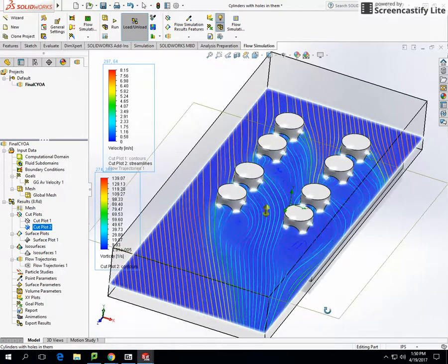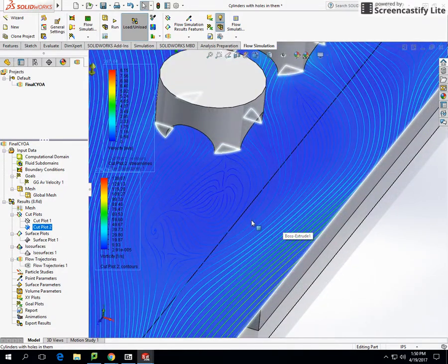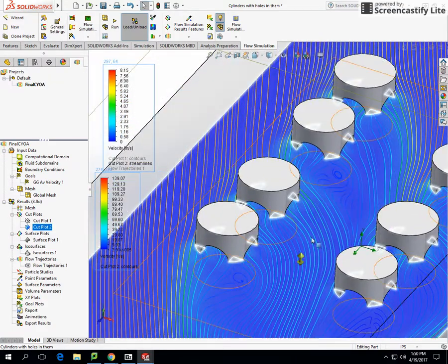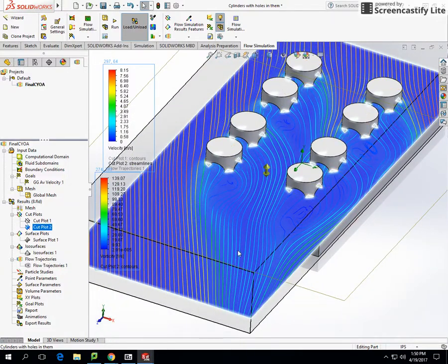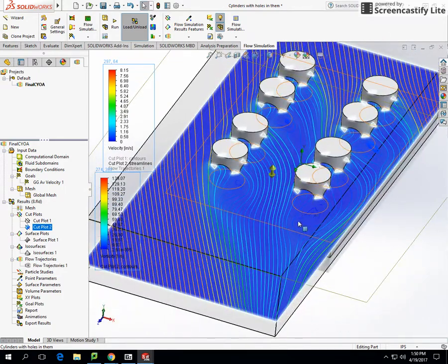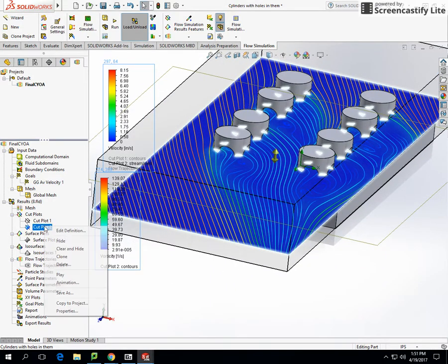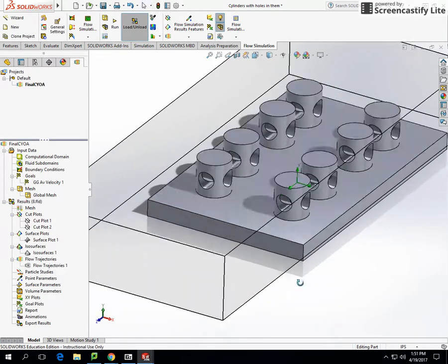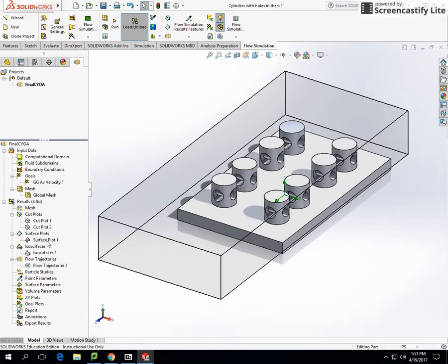This one is measuring both velocity and vorticity. So I have the contour showing vorticity and the streamline showing velocity. So these streamlines are showing the magnitude of the velocity. Darker is slower, red is faster, and then the underlying background color is going to show you the actual vorticity. So it's more vorticitous in the darker regions than in the slightly lighter regions out here, which is going to show you the eddies and all those sorts of things.